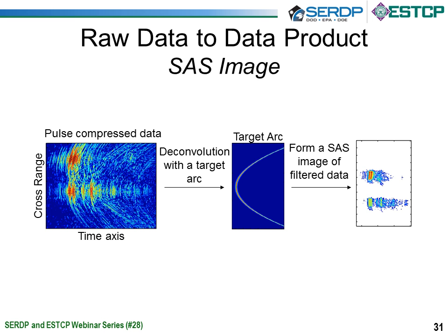Now, this is a little cartoon illustrating the beamforming process. There's many methods for doing this, but they all essentially amount to doing a spatially variant matched filter to deconvolve out the response of the aperture pattern that the synthetic aperture array has. And you can see the focused acoustic data on the right.